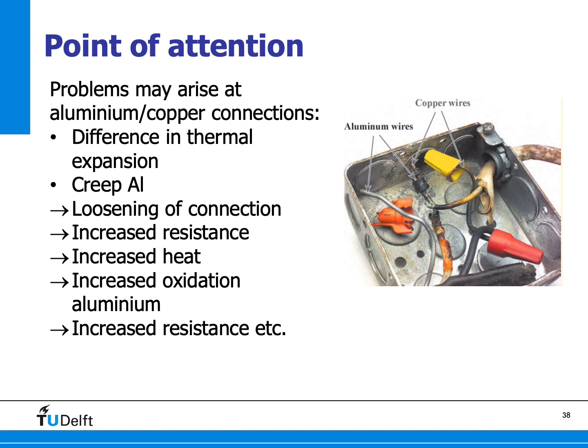At the same time, at higher temperatures, some creep may take place in the aluminum. That basically means that the aluminum is also deforming, changing its length due to the elevated temperature if there is some tension on it. So what can happen due to these two different factors?